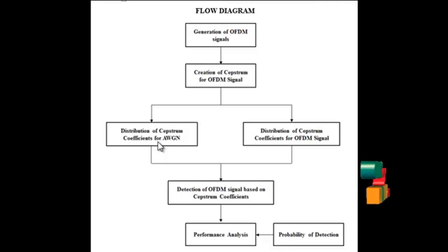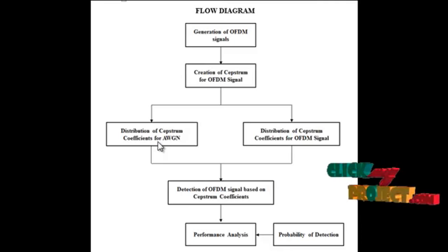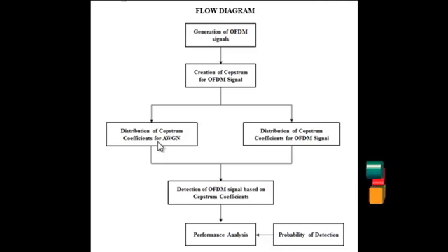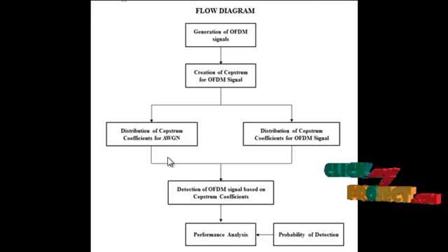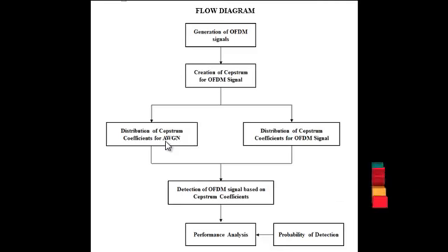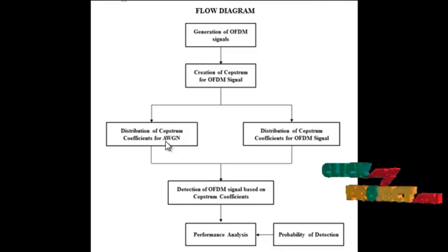Here only the presence of AWGN is considered. The probability density function for the circular log Rayleigh random variable is derived, and the log Rayleigh distribution is characterized by the property that all its central moments of order higher than 1 are independent of the location parameter.